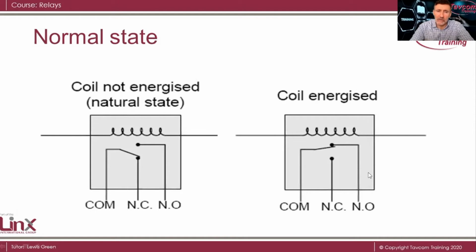So in its normal state, we would see a connection between common and normally closed, and in its energized state, we see a connection between the common and the normally open.